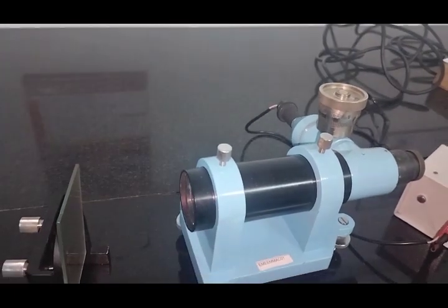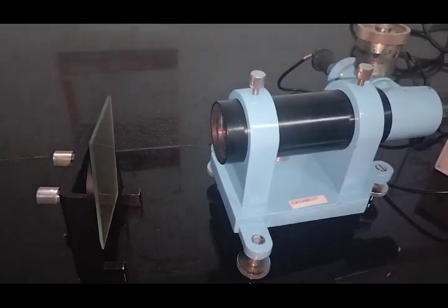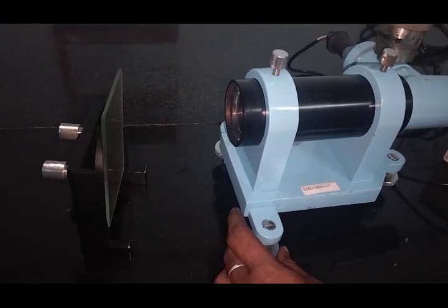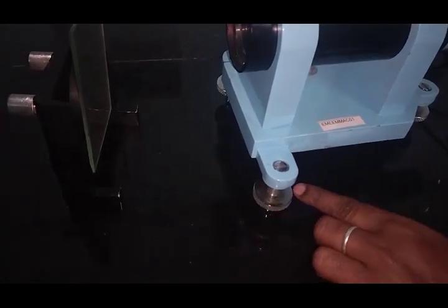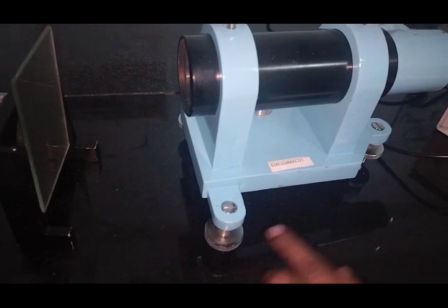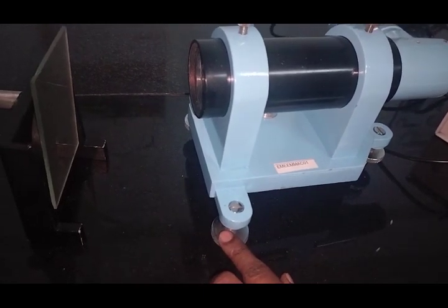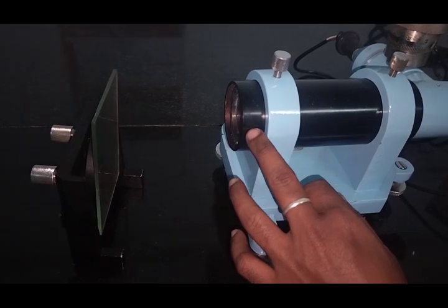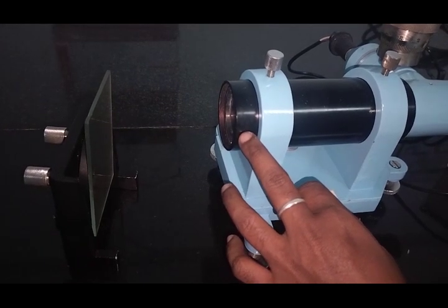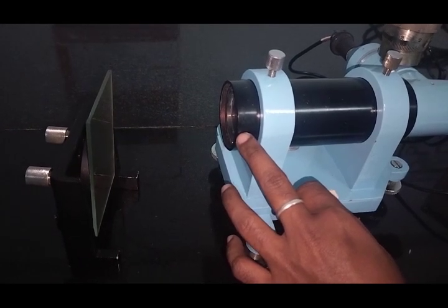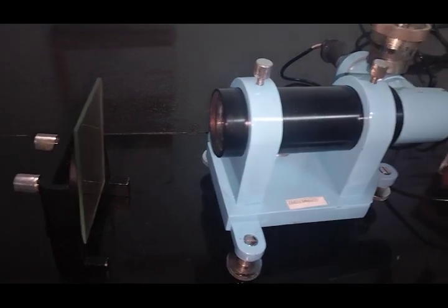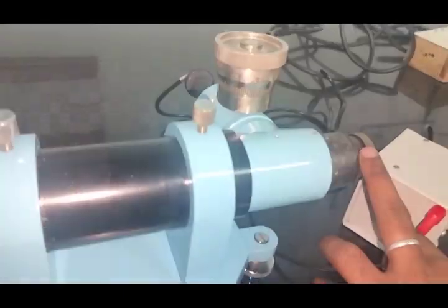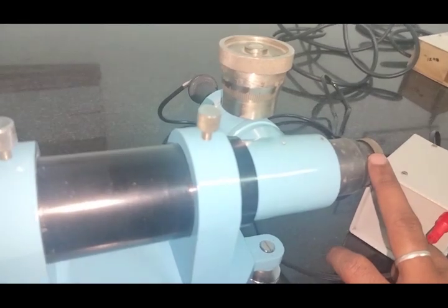On the procedure, first is testing the square with the autocollimator. Level the autocollimator unit and the standard table. This is the standard table we have to fix in the autocollimator. Then fix the optical scanner for straightening of the light. Then observe the measuring graticule through the eyepiece. We locate the eyepiece here so we can easily observe the measuring graticule.